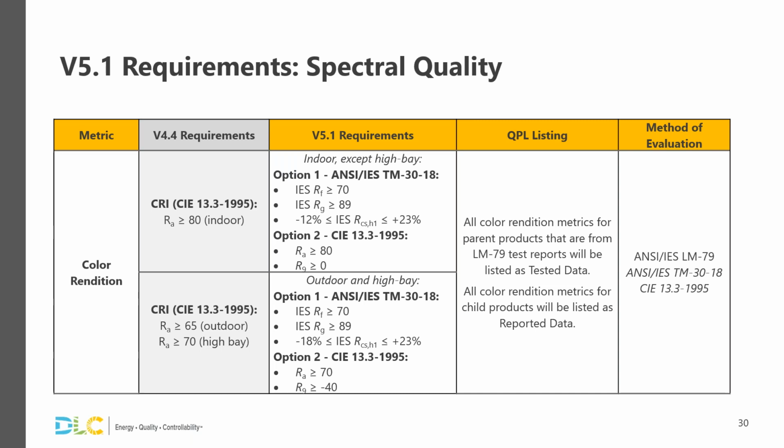Shown here, the indoor TM30 standard qualification requirements have been set to align with the minimum color preference thresholds of the new IES TM-30-18 annexes. Not only are the TM30 thresholds correlated to preference, but they've been shown to have greater energy saving potential over the traditional CRI. This is our first step toward transitioning to using color rendition metrics that can provide more insight into product performance. It's important to note that the IES TM30 annex that recommends thresholds is only for indoor applications.